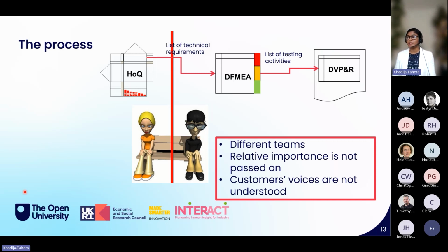When the tools are managed by different people and the information flow, or data flow, between them is not systematic, the importance identified in the QFD is not correctly or accurately transferred, or even transferred at all. With the complex FMEA process and its attention to the risk only, the risk priority number, as Andrew mentioned, the importance to the customer tends to fade.